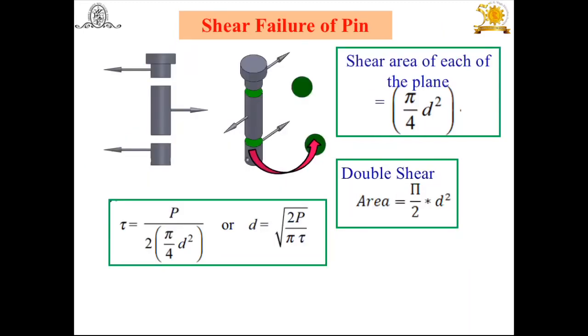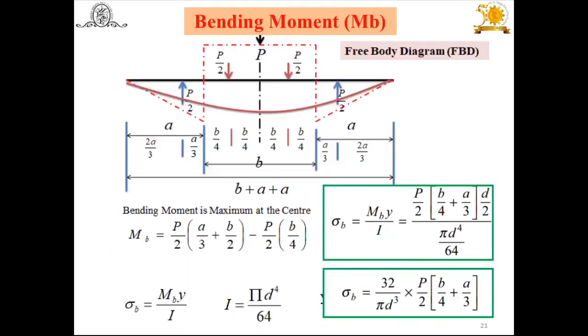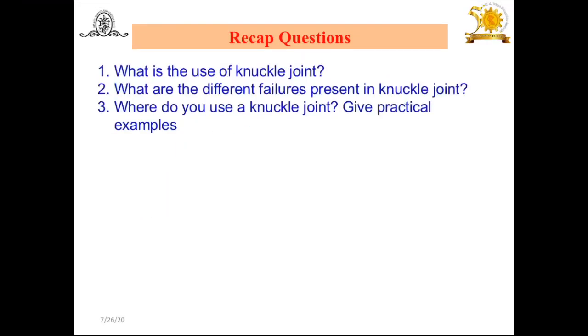That means to design a knuckle joint, you should know the capital D, the diameter. Then you should know the D0, the annular diameter, that is 1.1 times D. Then you can easily find the small d from the design of the pin. Then small a, small b using empirical relations in terms of capital D, and the pin head diameter, that is 1.5 times the small d.